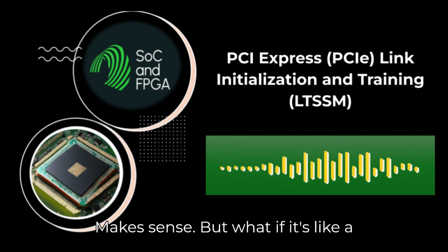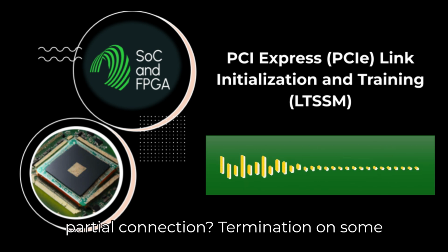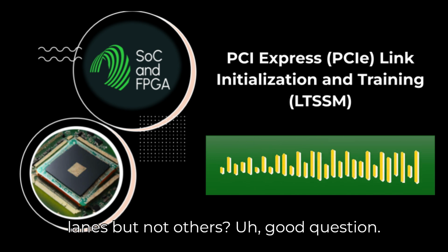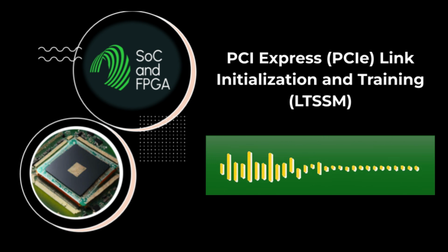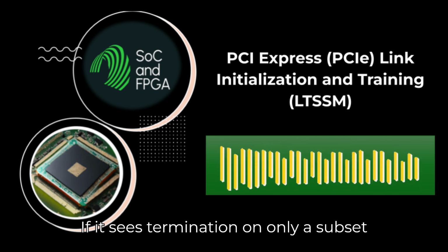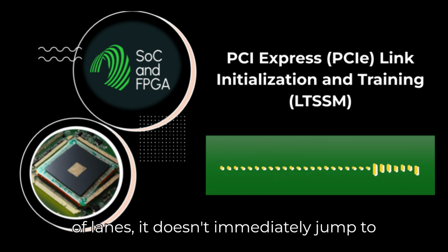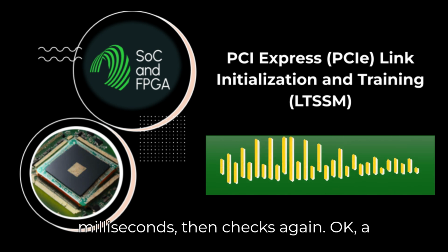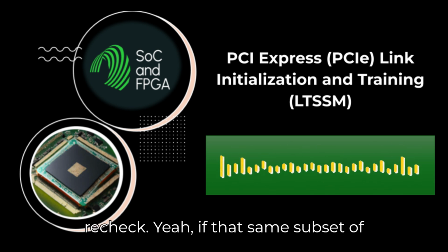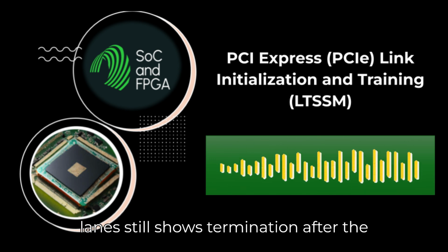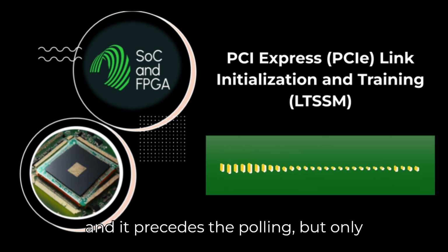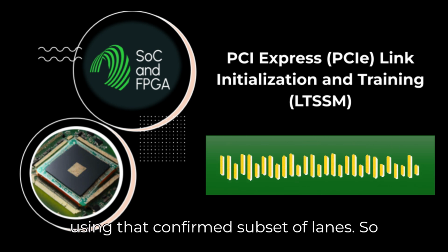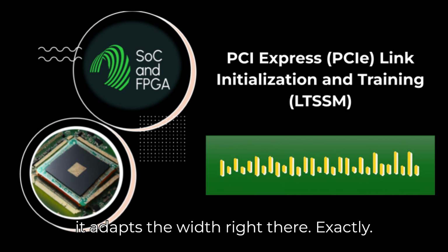Makes sense. But what if it's a partial connection? Termination on some lanes, but not others? Good question. That's where it gets a bit more cautious. If it sees termination on only a subset of lanes, it doesn't immediately jump to polling. It waits another 12 milliseconds, then it checks again. Okay, a recheck. Yeah. If that same subset of lanes still shows termination after the wait, then it says, okay, this looks stable, and it proceeds to polling, but only using that confirmed subset of lanes. So it adapts the width right there.